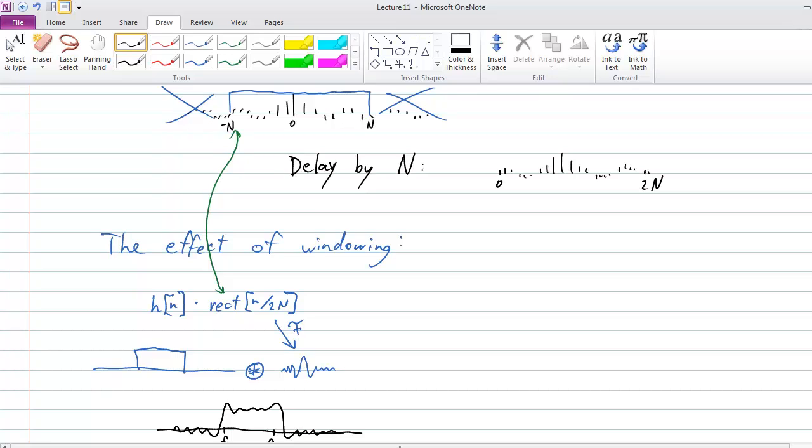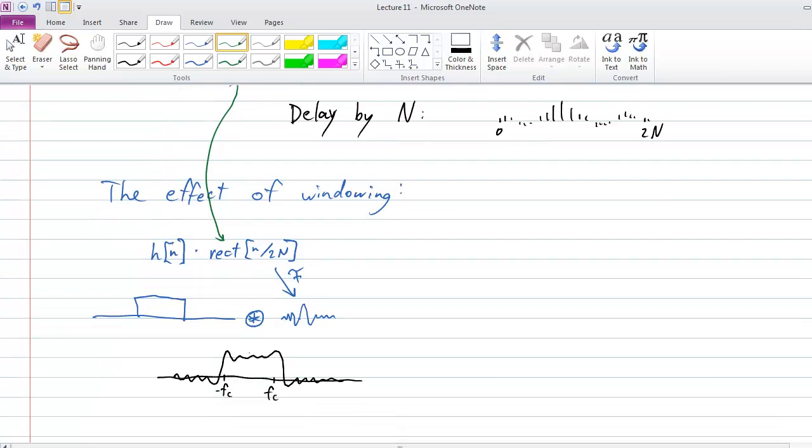Rather than giving you the ideal filter response that you thought you were designing, you actually have that ideal filter response convolved with the Fourier transform of your window. Okay, and for a rectangular window, that's going to be this discrete sinc. So you're going to get something like this. It's no longer ideal, but it's still a low-pass filter. It has a little bit of rippling in the part that you were trying to let through uniformly. And it doesn't cut everything off at the high frequencies, and it has sort of a transition period. Okay?